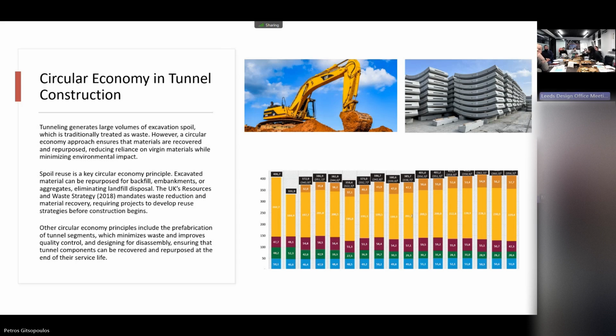Back to the tunneling though, a circular economy approach, we ensure that materials are recovered and repurposed, reducing reliance on virgin materials while minimizing environmental impact. Spoil reuse is a key circular economy principle. Excavated materials can be repurposed for backfill, embankments, or aggregates, eliminating landfill disposal.